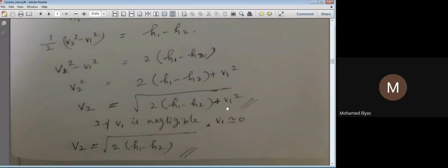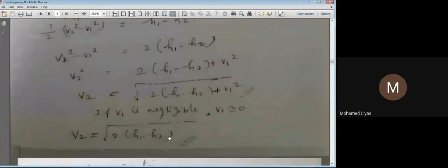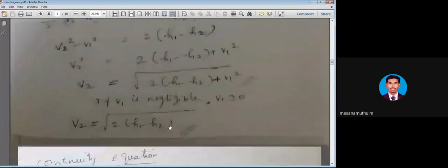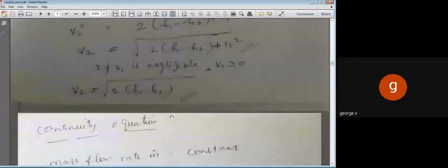So in that case, we usually neglect the inlet velocity in the case of a nozzle, because low velocity fluid only will be coming into the nozzle, as we have seen. When we neglect it, the equation gets unified, but the result will not be affected much as the velocity value is very, very less. Even if I use this, it is also correct. You can use both equations; this is only to simplify the equation. It is written, sir. Next, copy this. That will finish our class.